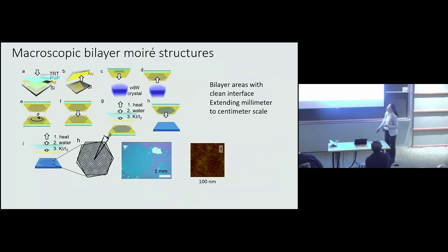So our trick is, we make the top gold very thin and the bottom gold very thick. The top gold is only around 50 nanometers, and then we can control the etching rate so that it etches the gold on the top and leaves most of the gold on the bottom. After that, we just flip it and put it onto the substrate. And then we play the same trick of removing the handling layers and etching the top gold again.